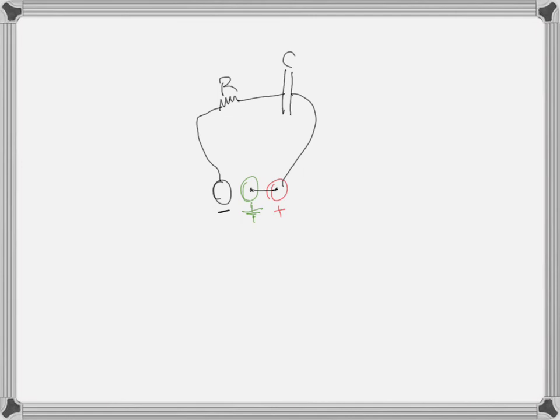Okay, so what I just did is I grounded the plus side, which isn't wrong. I can ground the plus side. So if I set this power supply at 9 volts, that now makes the high 0 volts and the low minus 9 volts. That's okay. It still works. But instead of being 0 volts to 9 volts, it's negative 9 volts to 0 volts. If instead I erased this black line here and I put a wire between green and black, then what's going to happen is now this one's set at 0 volts, and now this one's going to be plus 9 volts. Again, if the whole thing is 9 volts.